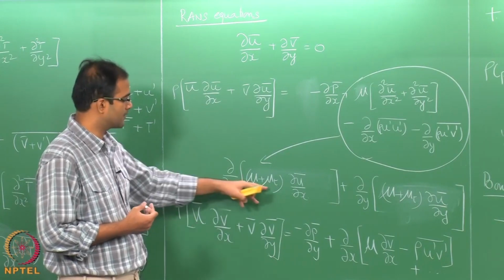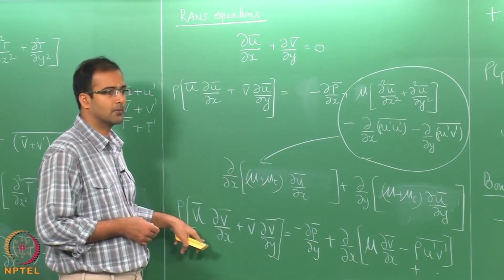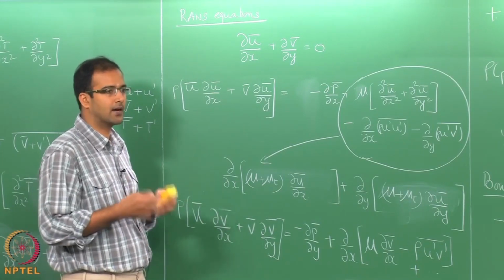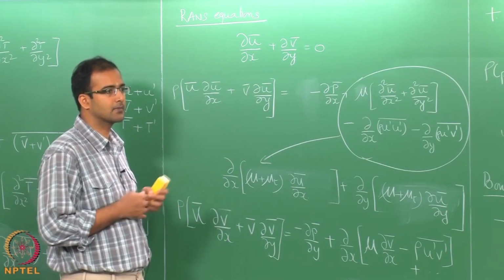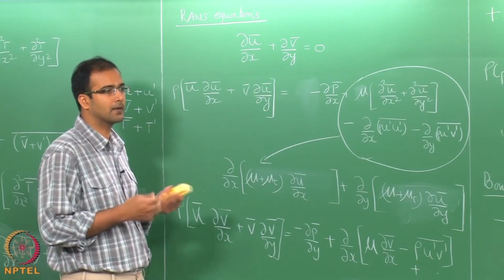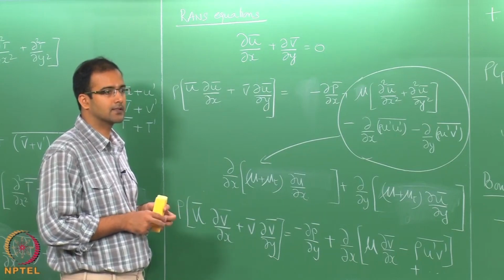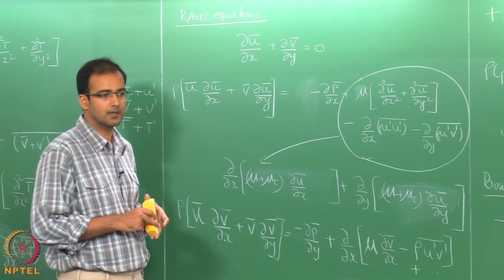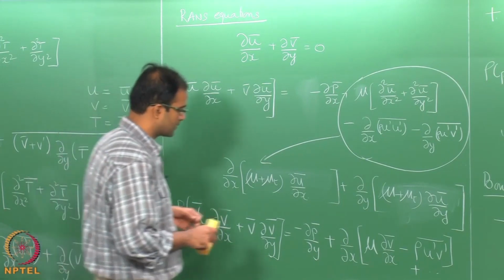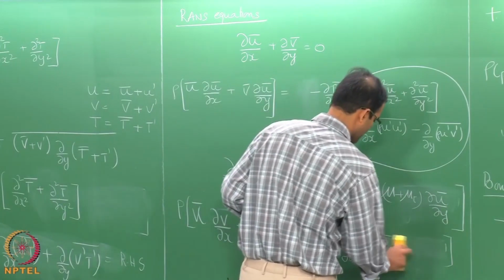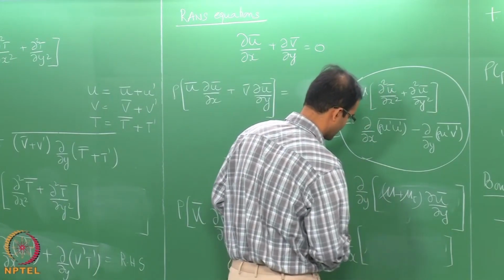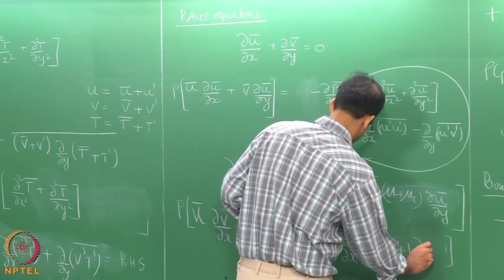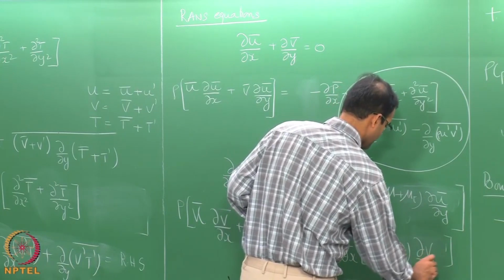Okay, so we are not using different mu t for the x momentum, y momentum, each derivative. Okay, because already this is an ad hoc hypothesis which is reasonably good enough. So, there is no point in complicating it. So, let us make it simple and see if it works, and most of the time with reasonable approximation it works. Okay. So, same way you can also use this as mu plus mu t into dV by dx.